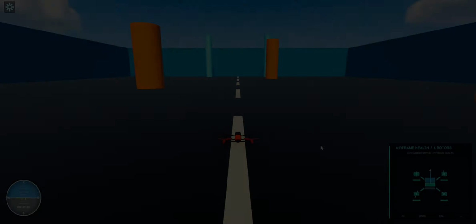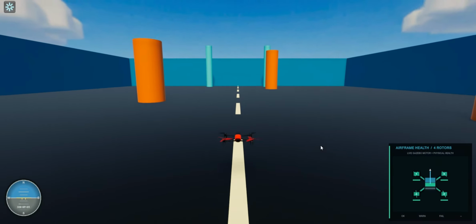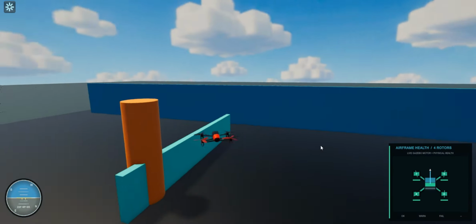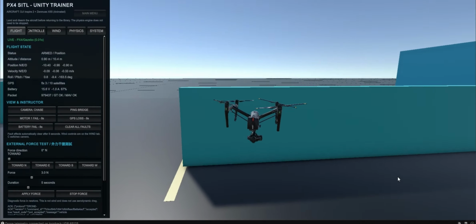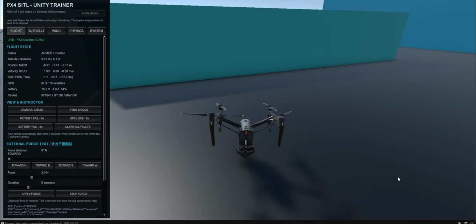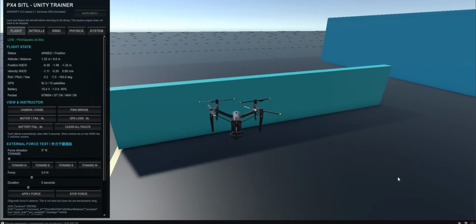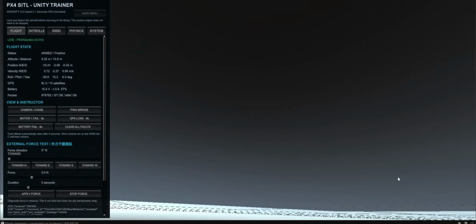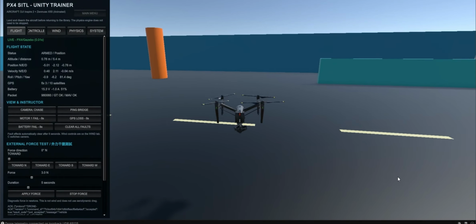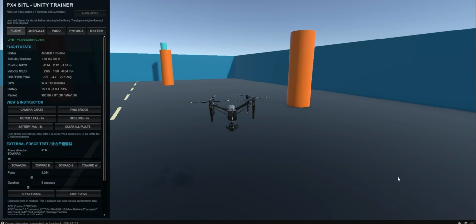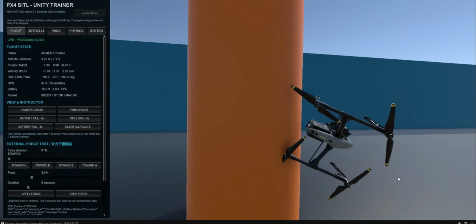The same aircraft model, flight controller, and map configuration are loaded into the simulator. Obstacles are not decorative. Collision is calculated by the physics engine and immediately affects the aircraft. This makes the editor useful for checking clearance, route difficulty, and failure behavior before a trainee enters the exercise.